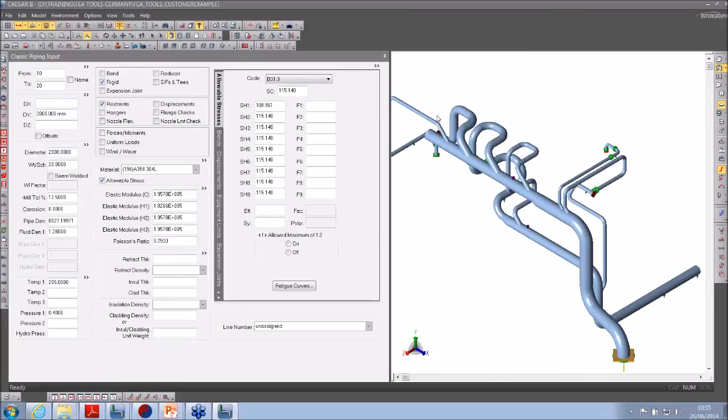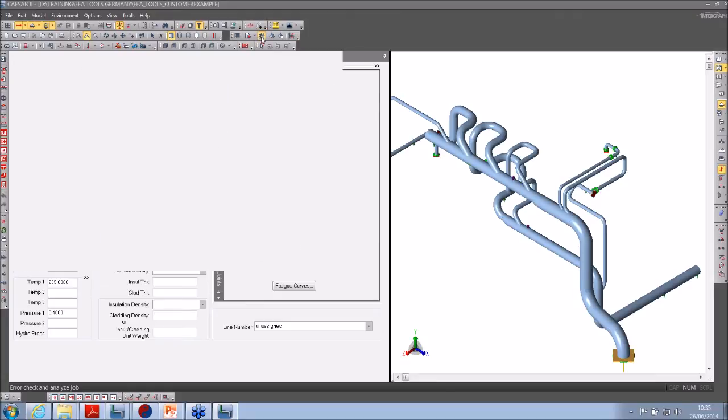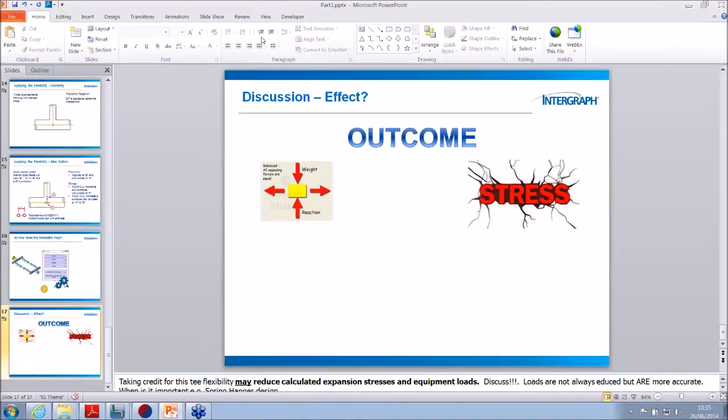So here this is our system, and first of all let's just run this system with the standard B31.3 CIFs that I've already pointed out we should be a little concerned about their accuracy, and see where we are. So I'm just going to do a batch run with the load cases that are currently set.